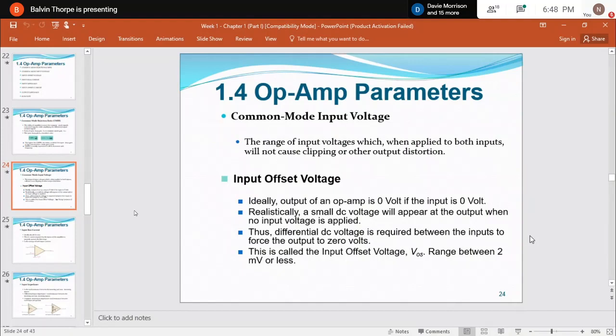All right. So again, for everybody, so that we don't get confused so early, the input offset voltage is a voltage that you're going to be putting at the input side of the amplifier to ensure that the output voltage is going to measure 0. Because we already know that it will not measure 0 under normal circumstances because of what is happening inside of the transistor.